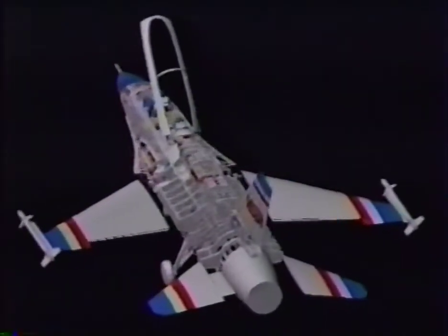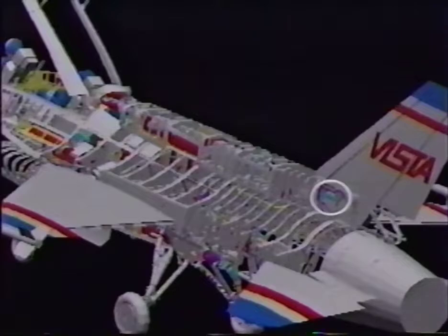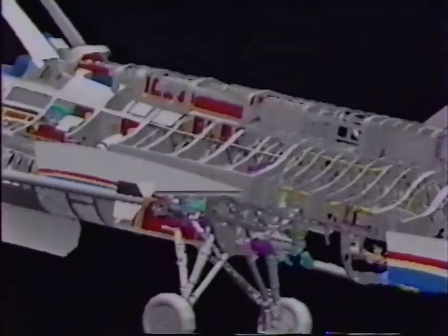The F-16 has 2 separate hydraulic systems which provide adequate flow, filtration, and operational safety. The core Vista hydraulic system was modified to accommodate the fully developed 6 degree of freedom configuration. Changes include the addition of 2 100 cubic inch pneumatic reservoirs to the existing flight control accumulators, increasing the system line size to allow higher flow rates, and installation of 2 increased capacity pumps.